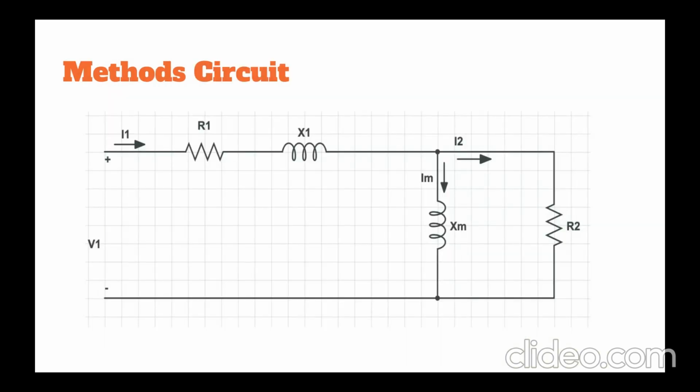The equivalent circuit of the LIM is based on the one-dimensional electromagnetic model. We analyze in detail the effect of the pole pitch, slip, and other LIM parameters. I1 is the per-phase stator current. R1 is the per-phase stator resistance. X1 is the per-phase stator slot leakage reactance. XM is the per-phase magnetizing reactance. R2 is the per-phase rotor resistance, and I2 is the rotor phase current.